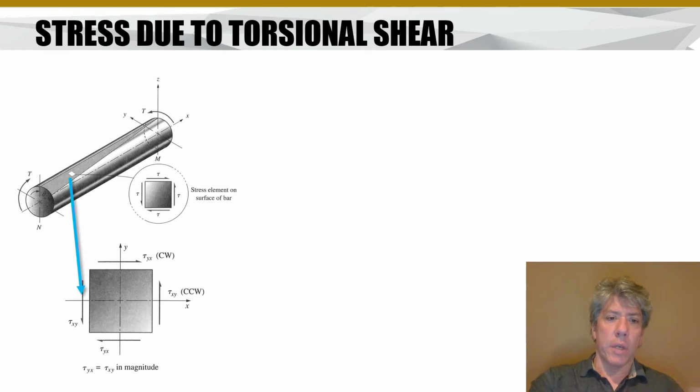And if we were to extract it, we might realize that these stresses would have names. We could name them, couldn't we? I mean, after all, if we have an X and a Y direction axis, then we could call the shear on the right-hand face tau XY. Now, what is this? Well, you notice there's sort of a pattern here. There's tau XY on the left and right. There's tau YX on the upper and lower.